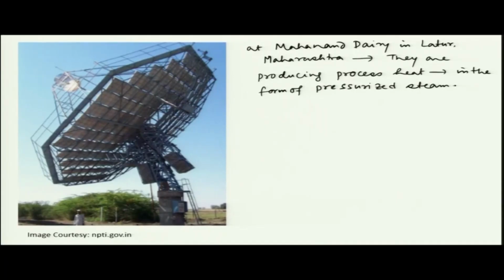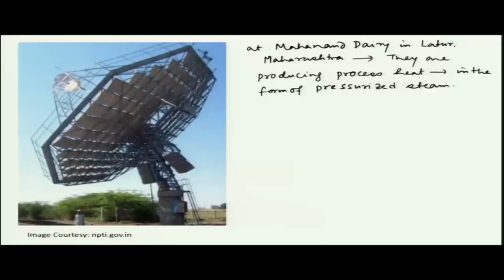Okay. So, for milk industry or dairy industry, what you need to have is process heat at certain pressure and temperature for the milk processing. Okay. So, for pasteurization you need to have the heating at certain pressure, you cannot go below that pressure because then the pasteurization process does not happen. Okay, so in this case what they are having is 20 bar pressure, okay, and temperature of about 180 degree centigrade.